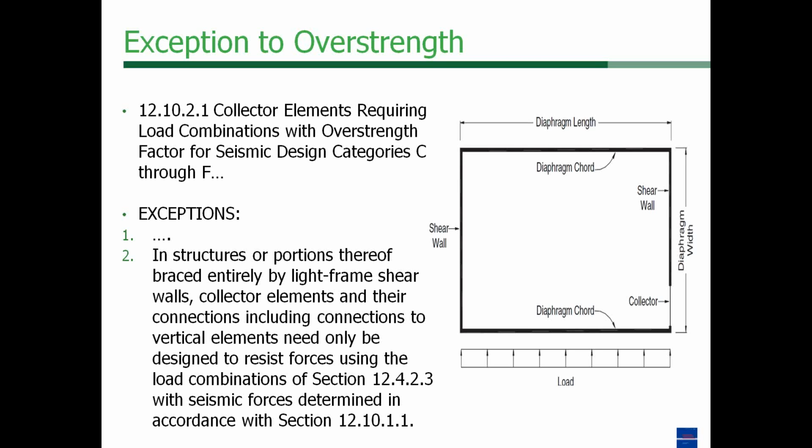And finally, in a wood frame diaphragm system, the panels themselves, as they're connected to the wood frame members, while they're not designed as the chord, they're designed to transfer shear forces. They really don't know that they're only supposed to transfer shear, and so they're probably giving some strength as well that's not accounted for in the system, or the system effect.